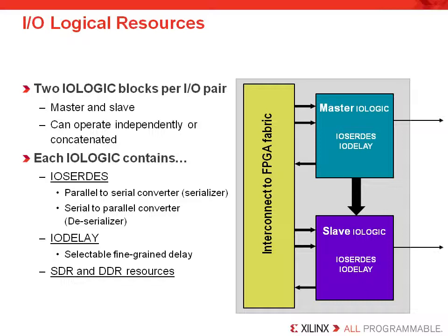Many issues that you would traditionally address by using the FPGA fabric are handled within these blocks. Tasks such as training pattern recognition, clock-to-data alignment, and crossing of clock domains between high-speed serial I/O and slower parallel clock domains can now be accomplished with the dedicated logic included in the SerDes resources, which is of course in each IOB. When we couple these resources with the I/O clock resources, as well as the regional clock routing resources, this feature becomes very significant and well suited for source synchronous applications. We will discuss the clocking resources in the basic FPGA architecture memory and clocking resources module.